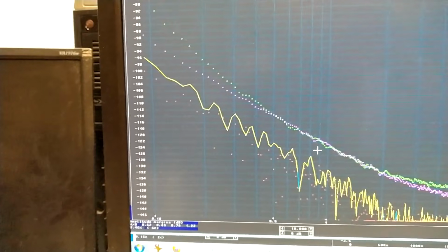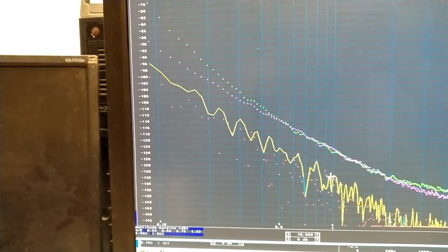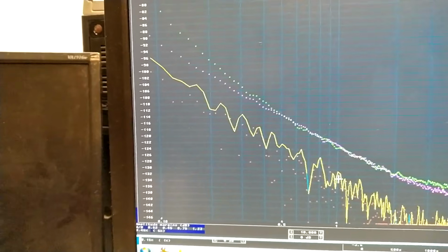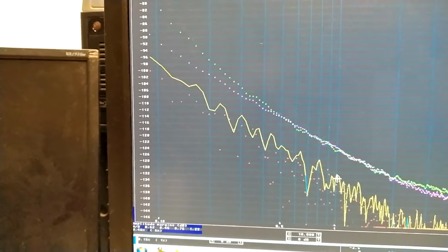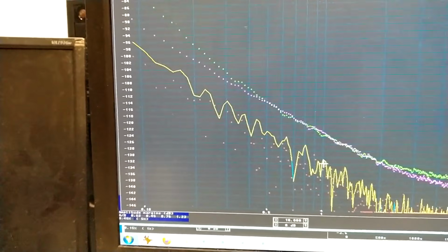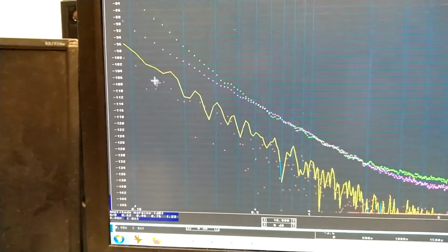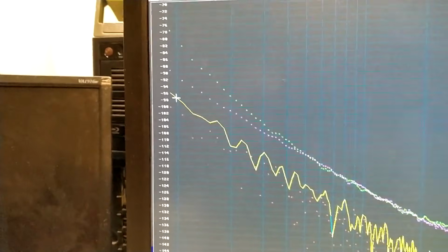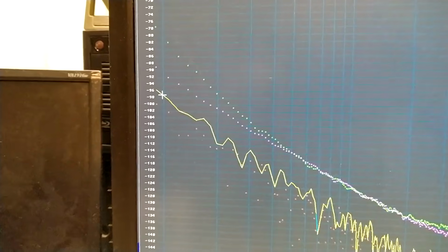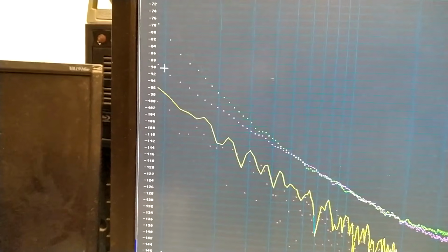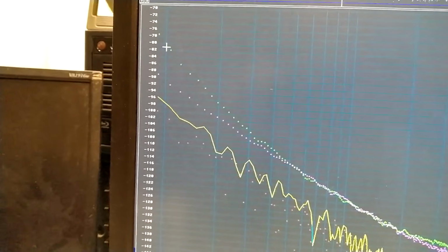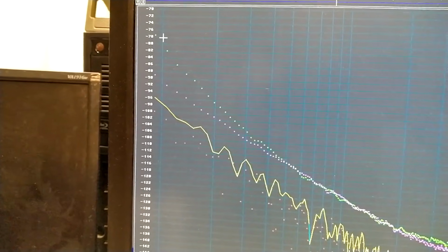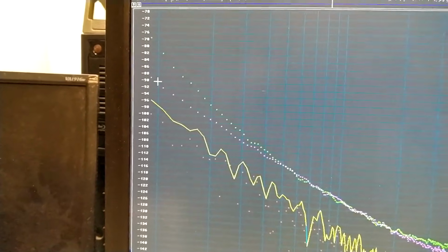And the higher resolution, going closer to the carrier, here I see at 1 Hz, about this level, that's minus 132. And at 0.1 Hz, it looks like minus 98. But here, the channel 1 noise is fairly high. It is about something from 78 to 90.